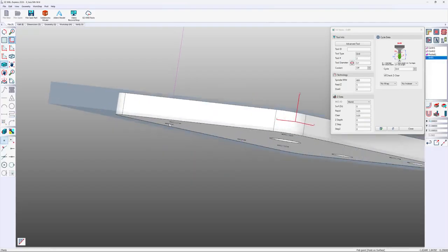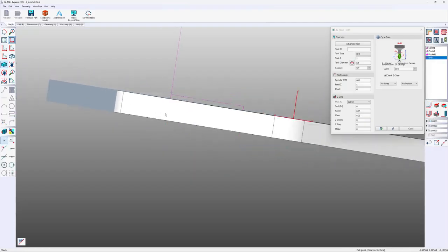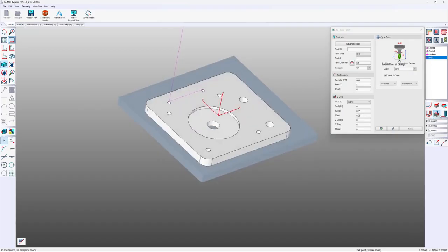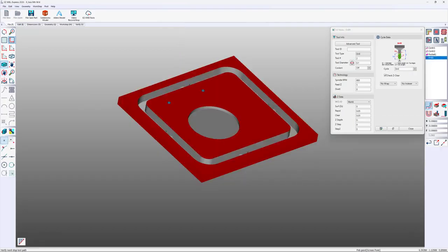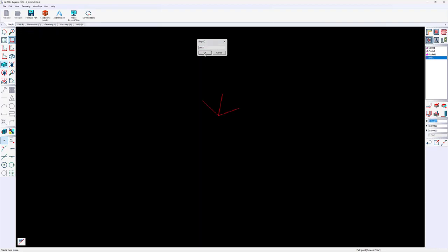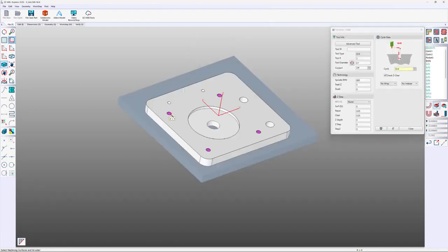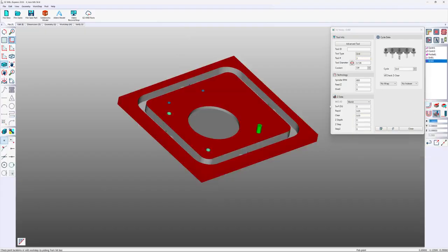As you can see here, create a second drill operation. We'll use these holes. There's 4 of them. Calculate diameter. Tool number 3. Now, as you can see, there's a change in color. For each tool number, or each tool, EasyCam changed the color in simulation. Helps you to keep track of what's machining what.